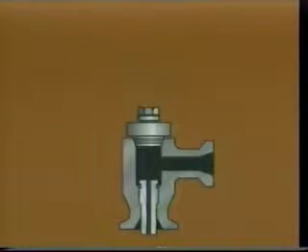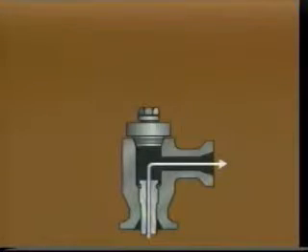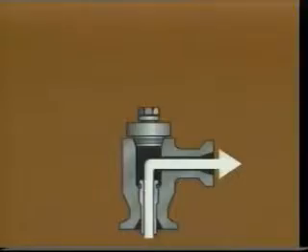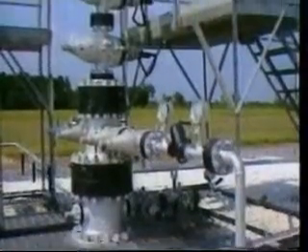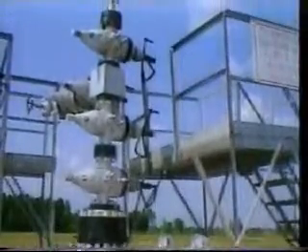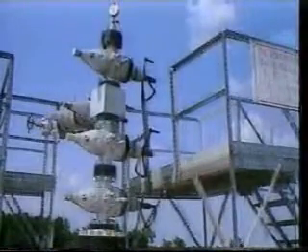The positive choke can employ the same choke body as an adjustable choke. The orifice size is controlled by the choke bean installed. A bean can be of any specified size, typically up to a 3/4 inch opening, and is designed to be easily and quickly replaced. Thus far, we have covered the major components of the Christmas tree for flowing wells: gate valves, actuator systems, and chokes.